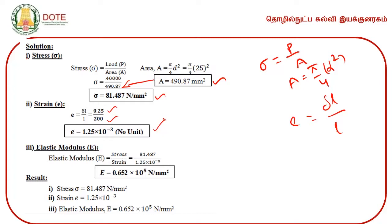Okay. The third step, we go to find the elastic modulus. What is elastic modulus? Elastic modulus E is given by stress by strain. What is the value of stress? We have determined 81.487 divided by strain. What is the value of strain? 1.25 into 10 to the power minus 3. So using the calculator we can easily determine the value as E is equal to 0.652 into 10 to the power 5 Newton per mm square.